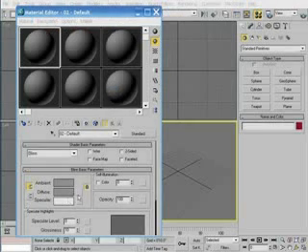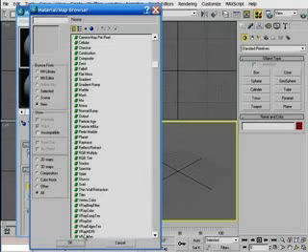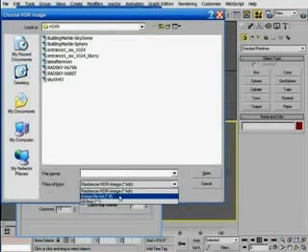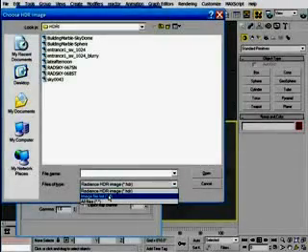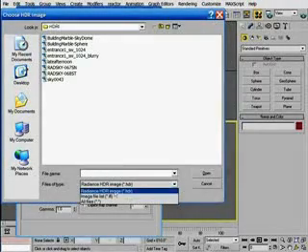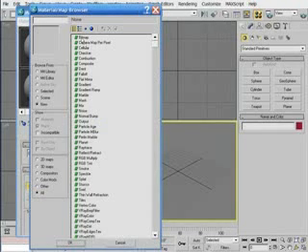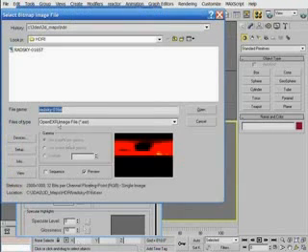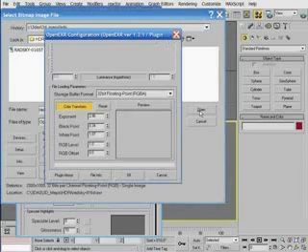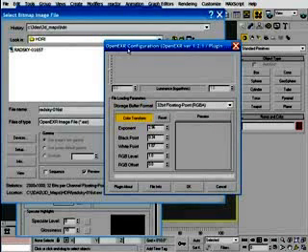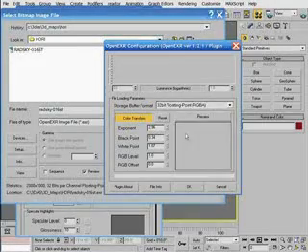But when you load the VRay HDRI map type in Max, and when you click on the Browse button and then the Files of Type drop-down list, you can see that the VRay HDRI shader does not support the EXR format type. You can still use it by loading it as a bitmap, but on a personal level, I still prefer the simplicity of the HDRI file because, by all accounts, it really yields perfectly good results. When you load an EXR file type, you're forced to do a little more work in the OpenEXR configuration dialog box to get the results that you need.